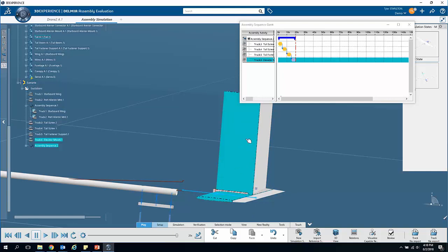Alright, let's say now, for some reason, I want this plate and this wing assembly up here to move off the boom at the same time. Well, we can go through the whole same process I did before. I know this last action was that big tail assembly here. So if I right click on this and delete that constraint, notice it didn't jump back 1 level, it jumped all the way back to the beginning. And that's not exactly where I want it. I need to recreate a dependency with this last action so that I get it to move in the step I want it to.